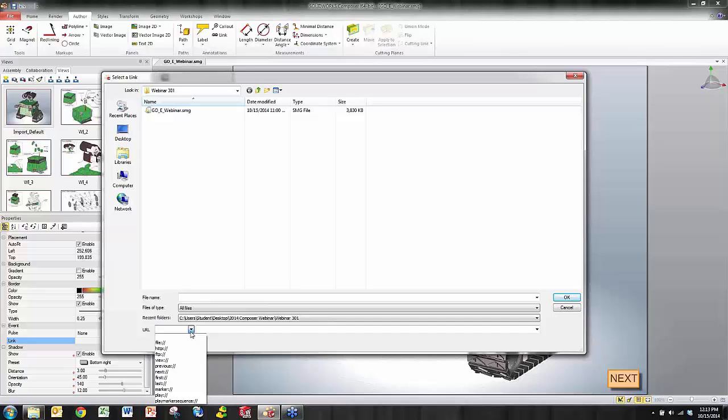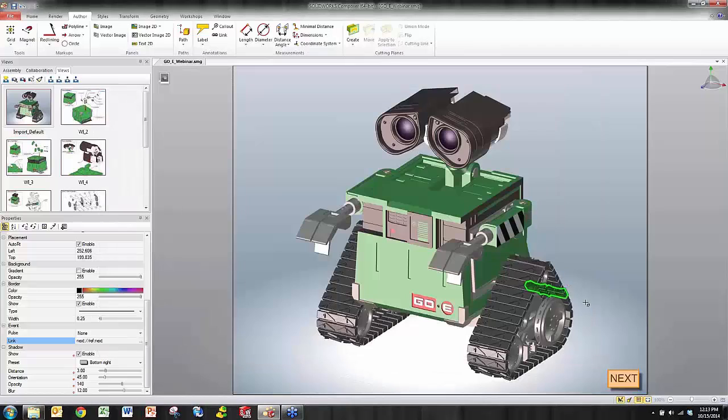So I really can have my animation broken out into different sections. Maybe I have a section for my arm assembly and I have a different section for my leg assembly. As long as I have the correct markers in my animation, I can have buttons that play those specific sequences. So here in this circumstance, I want to go to the next view. So I go ahead and say OK, and with this highlighted here, I'm changing this view here, this import default view. So I need to ensure that this Next button keeps all of its properties.